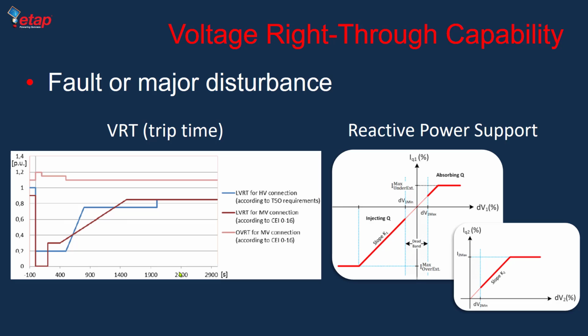There is a voltage ride-through, which means that if the voltage drops below, let's say, 90%, there's a curve that defines how long the inverter or the IBR needs to stay at minimum before tripping, as well as how much reactive power it needs to support, whether both positive sequence or negative sequence reactive power needs to be injected to the system. So again, this is called voltage ride-through, or VRT, capability that inverters typically have in their control.